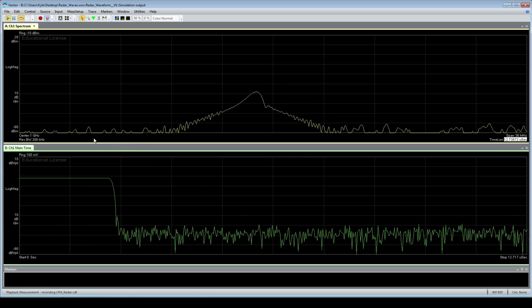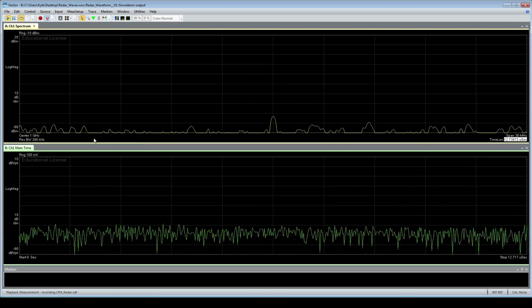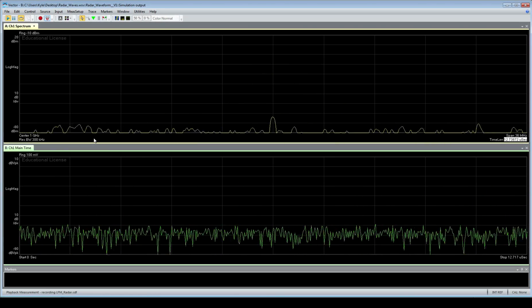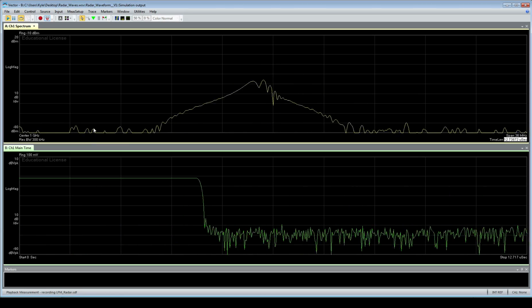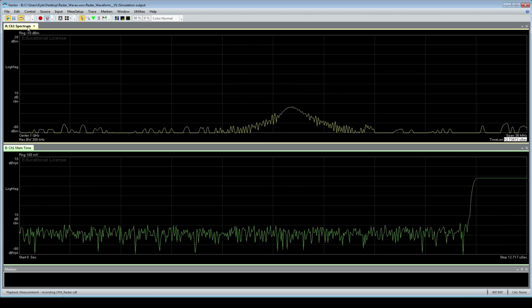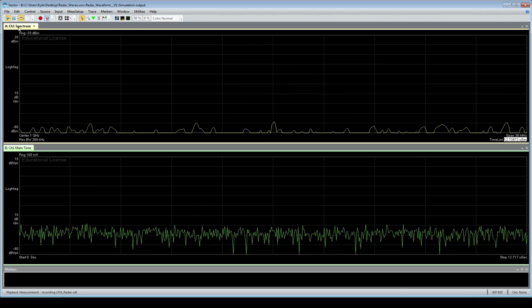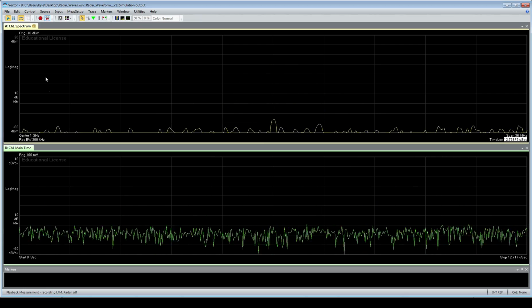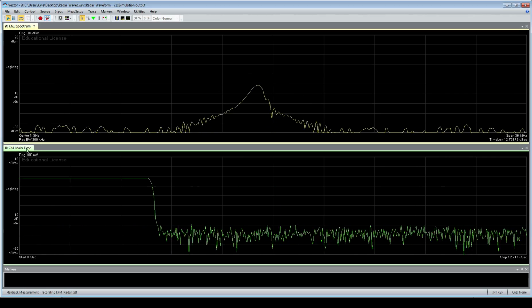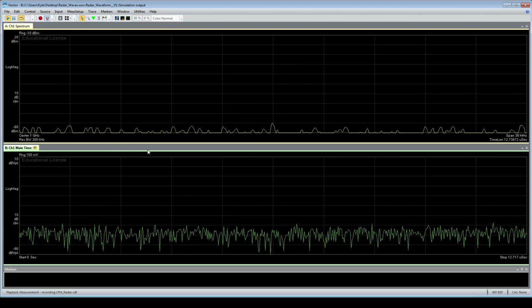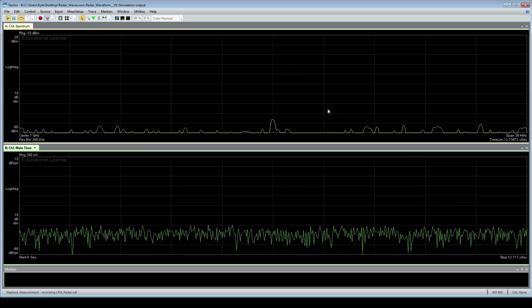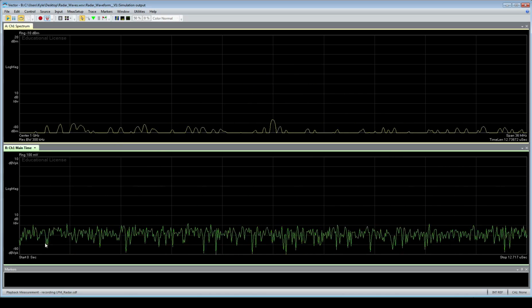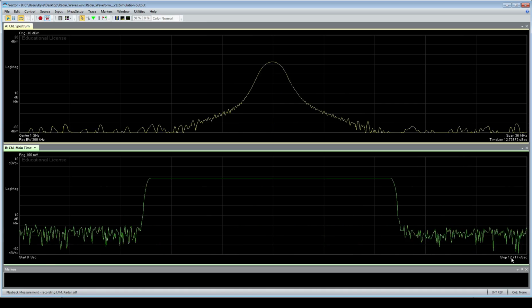And we're looking at 2 plots of it right now. The top one is the spectrum domain. That is a frequency domain signal we're looking at. And the bottom one's time domain. And we can see those at the plot traces for trace A. Channel 1 is spectrum, and we have some choices there. And the bottom one down here is channel 1 main time. And we can look at different aspects of the signal right here, but there's some details we really need to look at first. On the main time one, you can see it's got a start and a stop time.